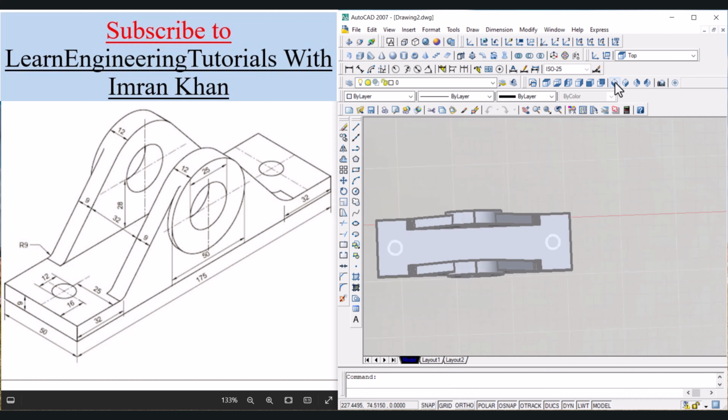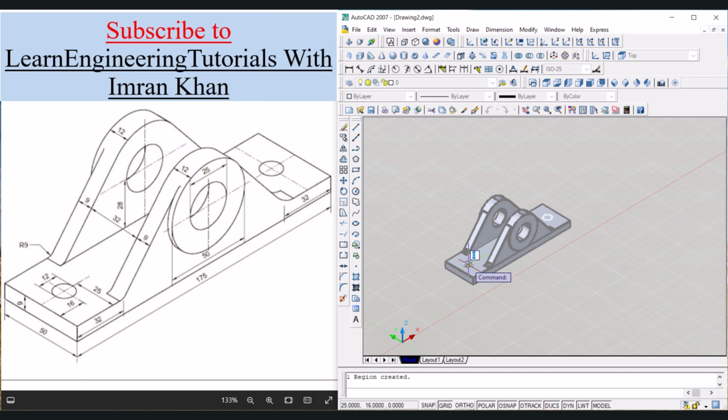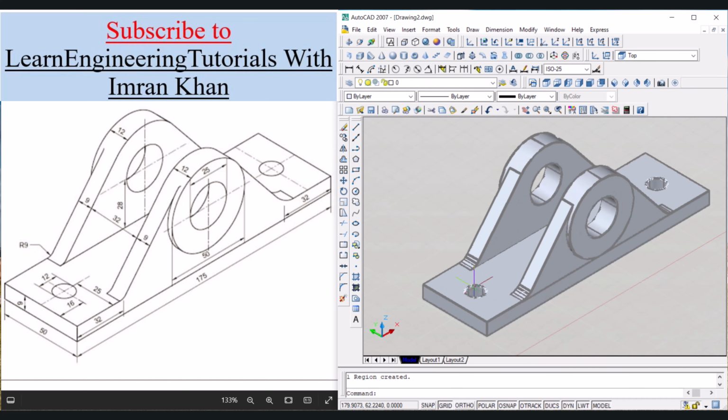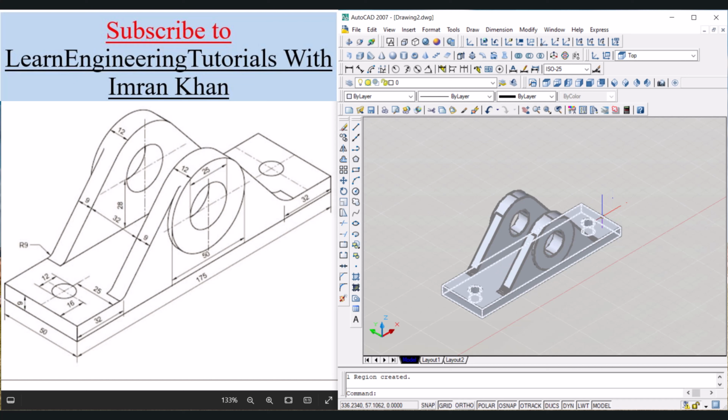Now click on press pull, bring the cursor inside this circle, click and move the cursor this way and click. Again click on press pull, bring the cursor over to this circle, click and move in this downward direction and click again. And now if you zoom it, we can see that the holes have been generated over here. So the object has been drawn correctly.